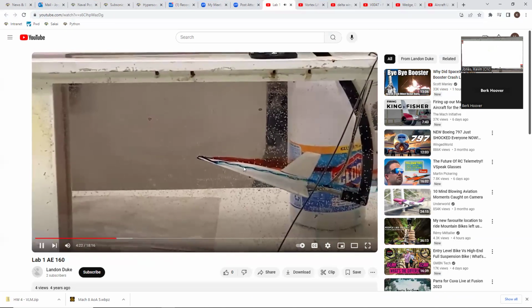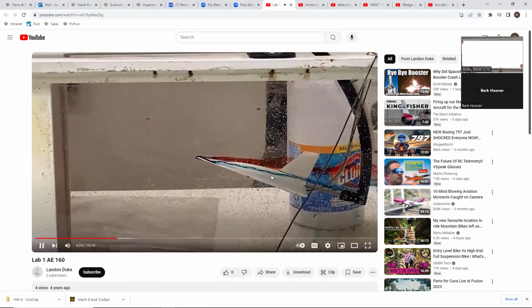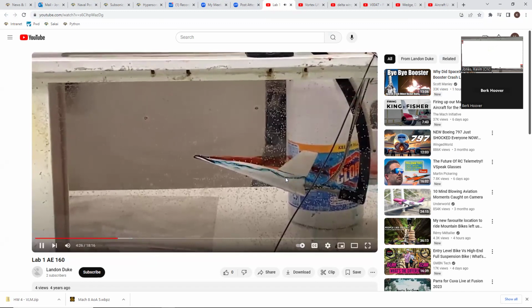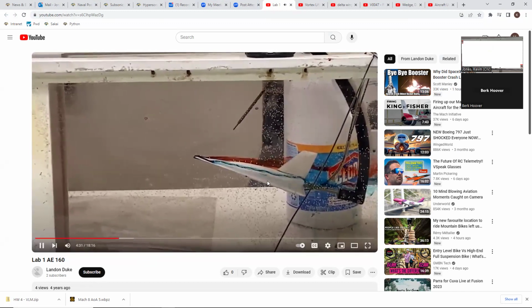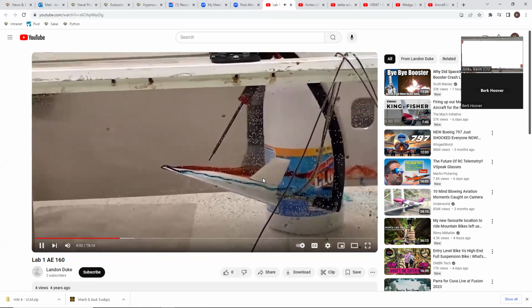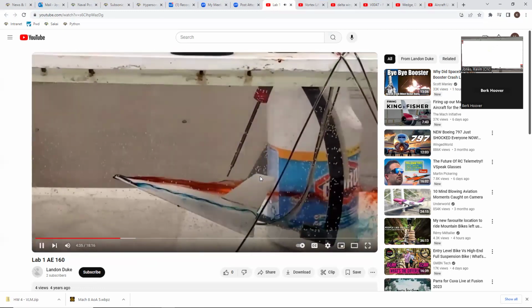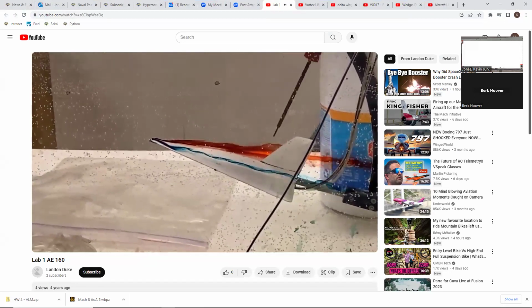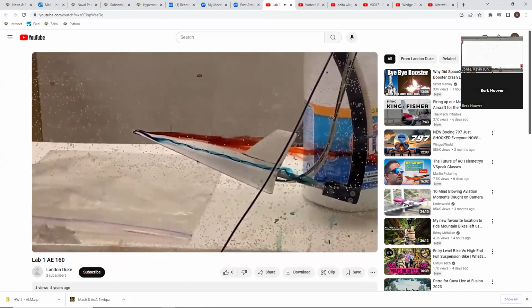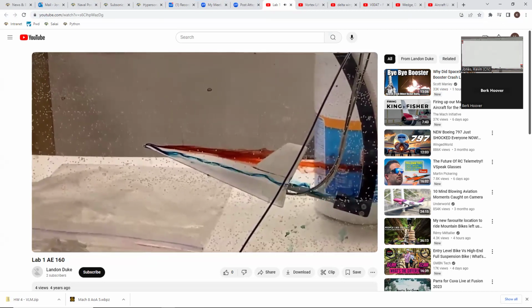So these vortex cores, they remain stable for some distance, but if the angle of attack gets high enough or the length gets long enough, they'll suddenly become unstable, and they'll either just dissipate really quickly, or they'll go through kind of a burst. It looks like they're trying to get around a bubble at the back.